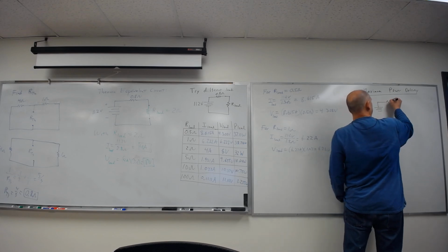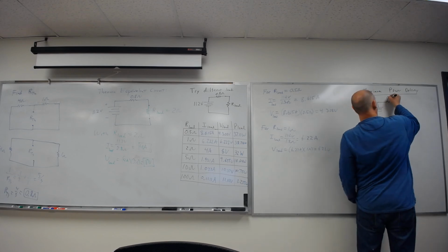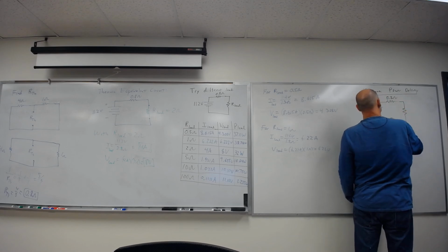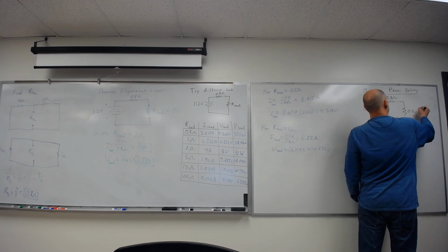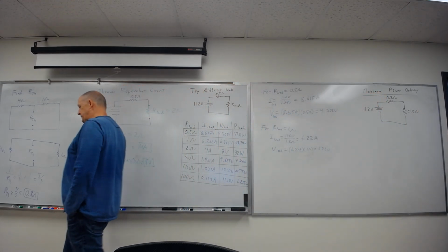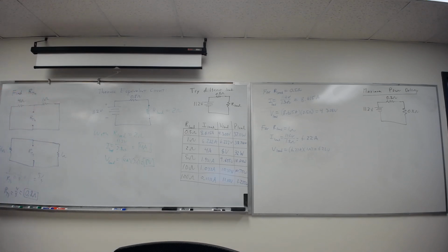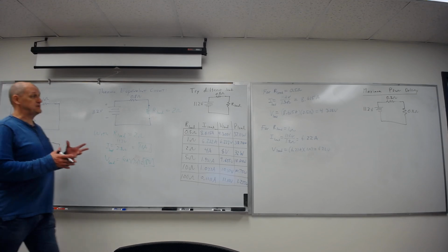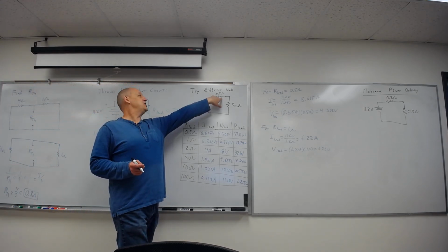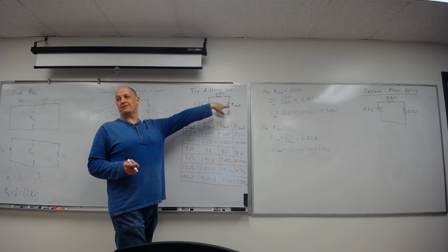It's something I can ask about now that you've seen it and I demonstrated. 0.8 ohms. The maximum power delivery I can have to something is when I make sure that the load resistance is equivalent to the Thevenin resistance. So this Thevenin thing is really important because I can switch the load real quickly. And it's also really important because when I found the Thevenin resistance, I know what I should set my load at to get the maximum power delivery.